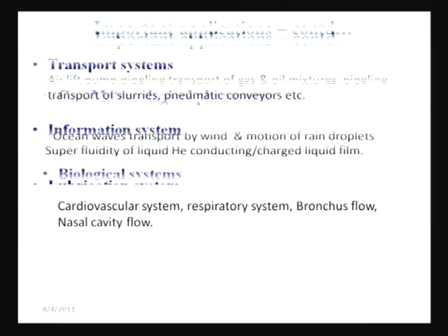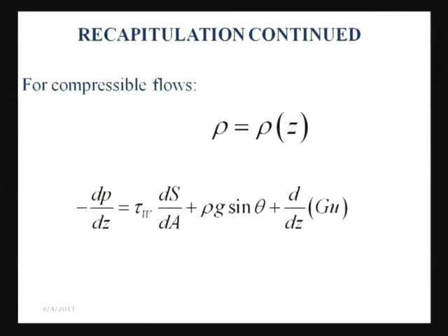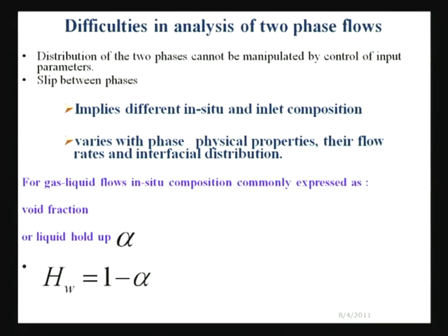This particular slip velocity, as I have already discussed in the last class, depends also upon the distribution of the two phases, and of course, it varies with a large number of parameters as we had discussed. Okay. So, since it governs the slip, it governs the heat, mass, reaction kinetics, it governs everything of two phase flow. The first thing which we should study is the distribution of the two phases and how it varies with different phases.